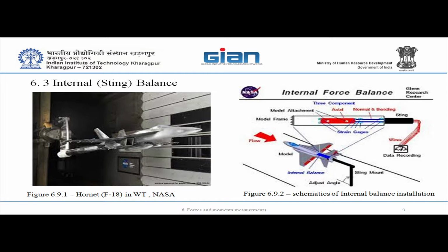If you start loading your balance far away, you get parasitic moment right from the beginning, and you lose a lot of resolution. If the center of pressure comes too near one of the cells, then the accuracy will deteriorate. But you don't use only one cell. You use several, one for each component, so it won't make a big difference.